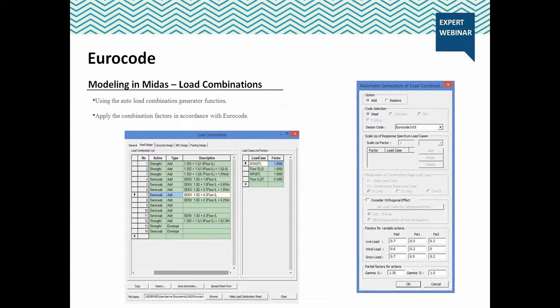This generator references the Eurocode and applies the combination factors to reduce the design values when they add together, creating different load cases to be analysed on the structure. A particularly useful design tool is the envelope combination feature. An envelope combination automatically selects the worst case combination for strength and for serviceability.